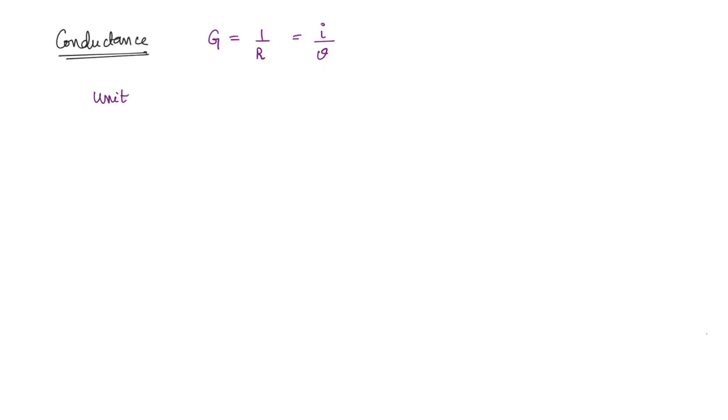And what about the unit? There are two units that we use in practice. The first one is called mho, okay, so it is the inverse of ohms. Just invert it. Or it is also called Siemens, and the unit is capital S. If it is small s, then it is seconds, which is the unit of time. For conductance, the capital S is used for its units.